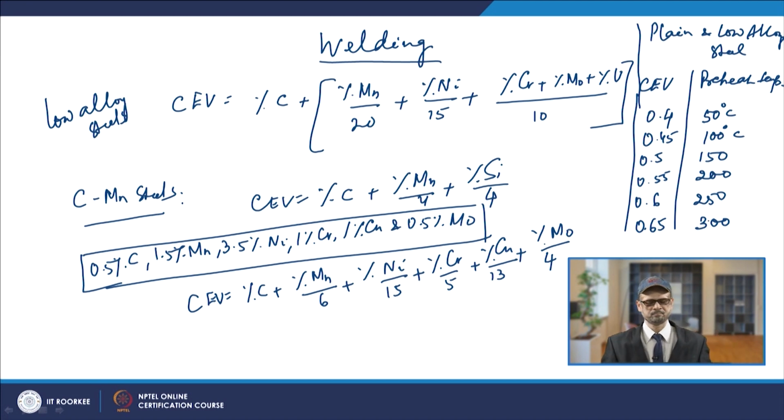So, basically the preheat temperature requirement goes on increasing as the carbon equivalent increases. You can see that not only carbon is important in deciding how it will affect the weldability, because when you do the welding, you will have to have some preheating.